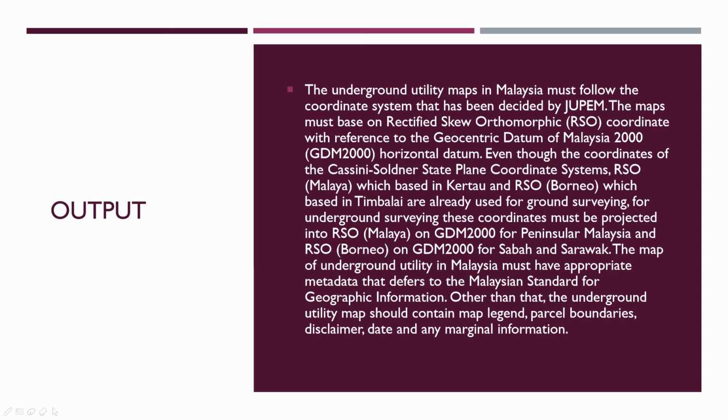The map of underground utility in Malaysia must have appropriate metadata that conforms to the Malaysian standard for geographic information. Other than that, the underground utility map should contain map legend, parcel boundaries, disclaimer, date and any marginal information.